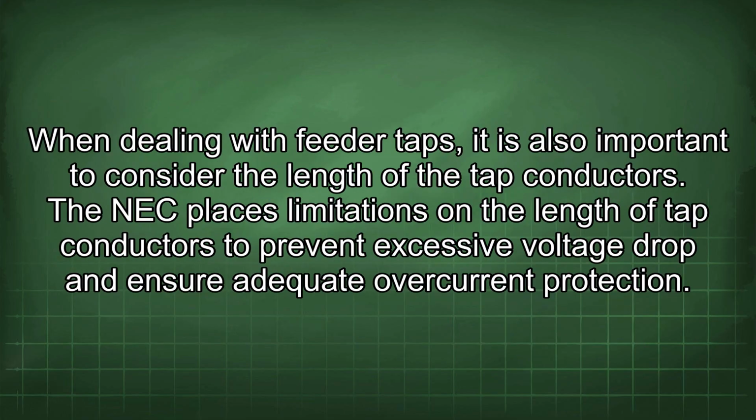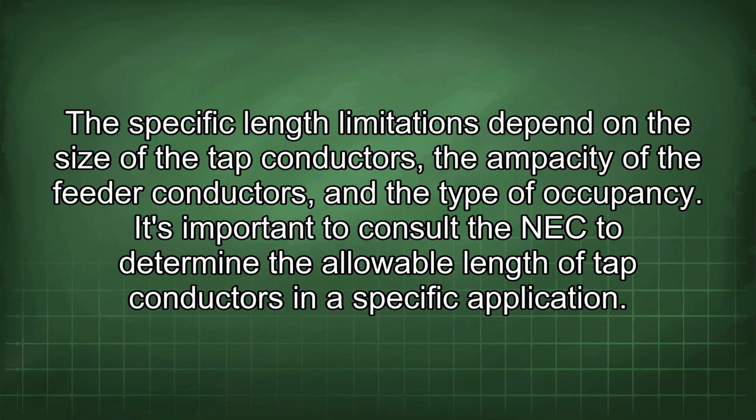When dealing with feeder taps, it is also important to consider the length of the tap conductors. The NEC places limitations on the length of tap conductors to prevent excessive voltage drop and ensure adequate overcurrent protection. The specific length limitations depend on the size of the tap conductors, the ampacity of the feeder conductors, and the type of occupancy. It's important to consult the NEC to determine the allowable length of tap conductors in a specific